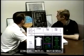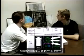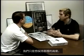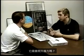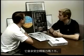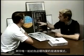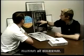Let's combine autothrottle engagement to some of our vertical modes. Okay. Start with altitude hold, cruise, and altitude constraint. What kind of autothrottle engagement mode would you have? Okay, they're basically the same. We're just trying to hold an altitude there, and we don't know what thrust that's going to take. Is it going to take climb thrust? Definitely not climb thrust to maintain it. I mean, unless we're at our maximum altitude. Is it going to take idle thrust? No. If we have idle thrust, we're coming down. So it needs some thrust in between there, and the only one of these that can give me that is speed mode. So all the altitude holds are associated with speed.